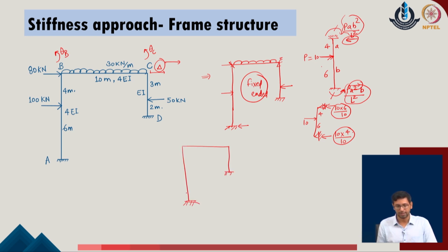As a next case, we come up with the similar problem and we consider that for the same problem we will release the first degree of freedom, which is the theta b in the given problem. So, as we release the theta b in the given system, we have this joint which will undergo the rigid rotation of the amount theta b, the common value of theta b for both the members, and corresponding to that we can define now the deformed shape of the given system, at which we will be able to generate the fixed end moments of the given system.